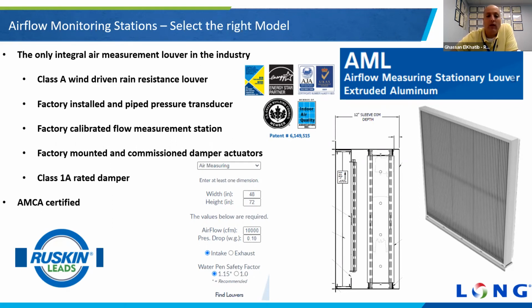The beauty of this system is it's all AMCA certified. So you've got a Class A wind-driven rain louver, and a Class 1A rated damper. Again, everything is factory mounted, commissioned and calibrated.